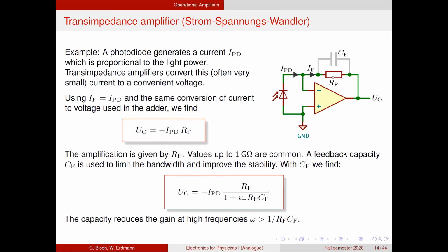In order to make the circuit stable, an output voltage change must be felt here on the input. Now, if this resistor is huge, gigaohm, then you have to change the output voltage by a lot. But in order to make it stable, the transient can be transmitted through a capacitor, such that the input already sees some change faster than through this large resistor.